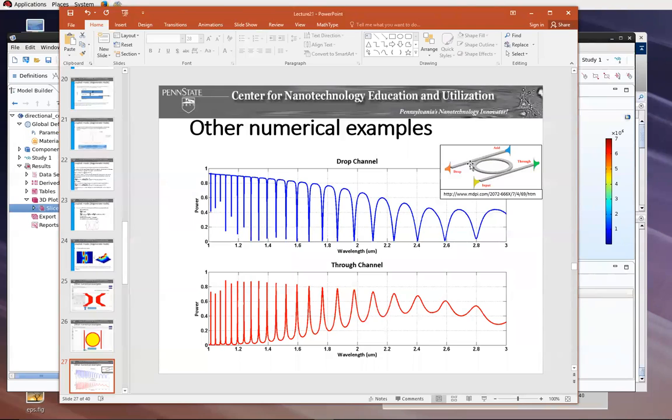So the light should have certain wavelengths to resonate inside this ring, and as you might already think, it has a lot to do with the diameter, I mean the geometry, of the ring resonator. So the data on this line will be dropped for some wavelengths, and it will be transferred to this side for again some wavelengths.